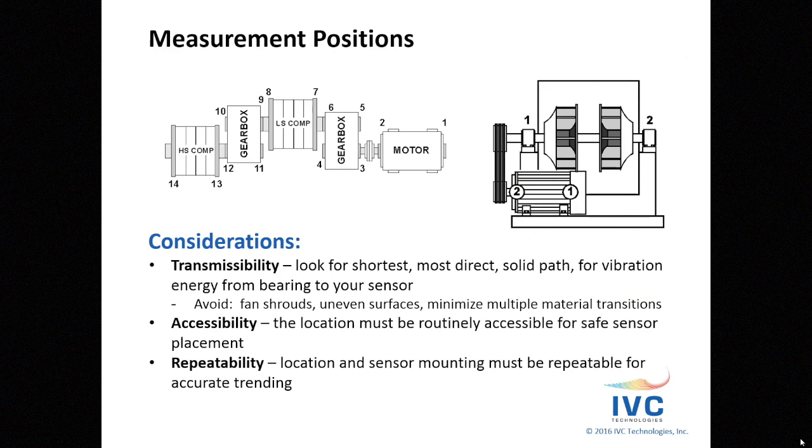One of the things that might be very important, what measurement positions are you going to have to accommodate? Considerations like transmissibility. Look for the shortest, most direct solid path for vibration energy from bearing to your sensor.